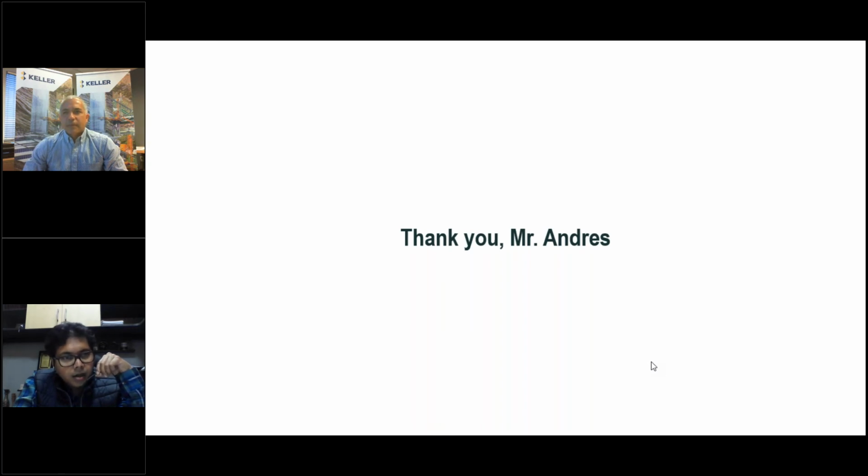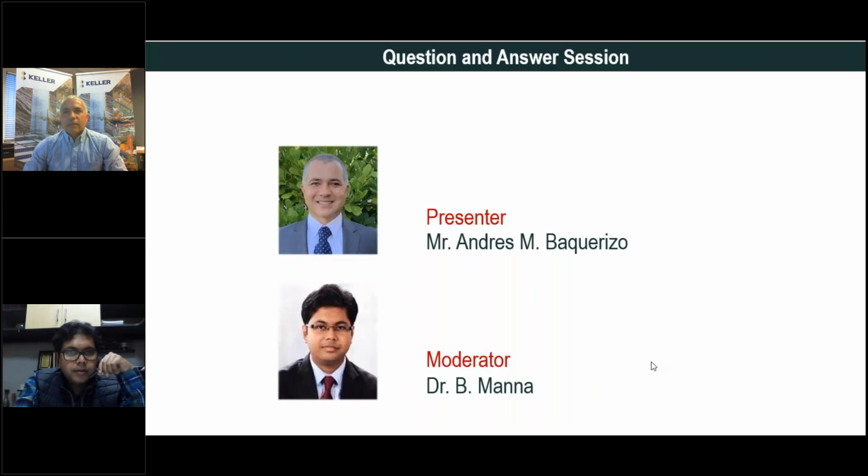The second question is, how is verticality of the reinforcement maintained? I already responded to that with the spacers. Because it's hanging in the air, it's going to be plumb by gravity, and as it's going down, the spacers will get it in the right place.